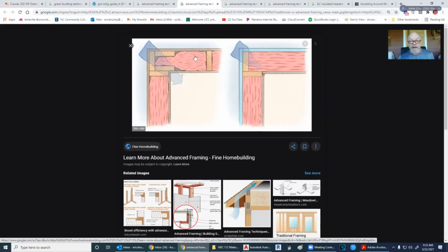Glass itself is a conductor, but when we use it in a fluff like this, we're causing a lot of air pockets in here. And that is where we get the insulation, is all those air pockets. So when we're squeezing it together, we're making smaller air pockets. In a sense, we're getting back to a solid piece of glass. So corners like this with the clips on there are better to use.